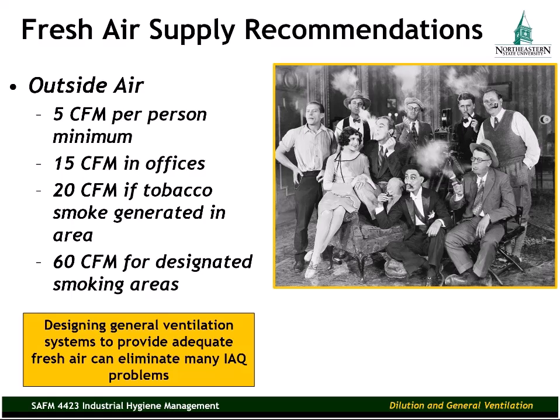Again, it all starts during the design phase. But let's say we're working in a building where the system's already in place. Then we need to do our investigation, identify the volumetric airflow into the space, and if it's not good enough, if it doesn't meet these recommendations, then we need to think about making changes to the system. Again, this fresh air can eliminate many indoor air quality problems.